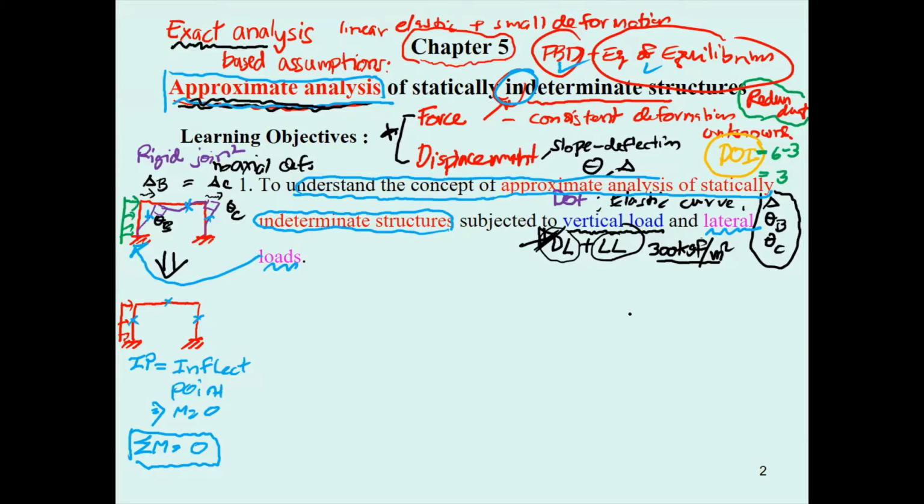You have to determine the loads carefully. If the loads are wrong, your analysis will be wrong, and your design will be wrong. And again, I should mention that the dead load and live load must follow the building code, not the design code. The design codes that you use are not legal, but technical.